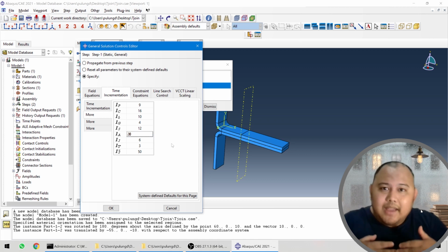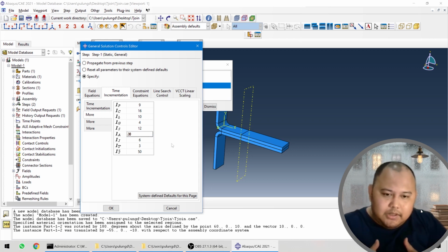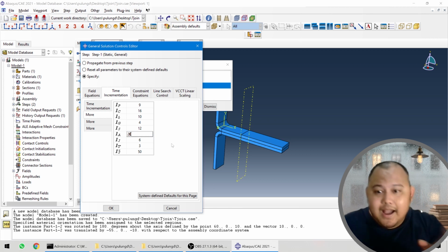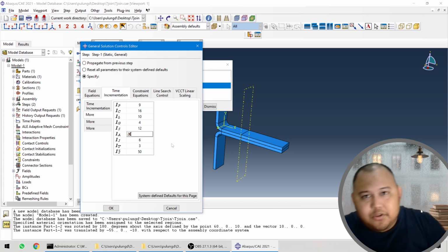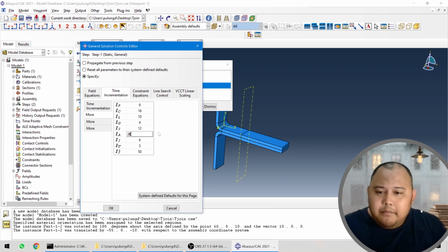Okay, so for a certain note that you gave, Abaqus might need to do it in so many very small increments, right? So the IA, on the other hand, or the IR or I0, is basically how many iterations you allow Abaqus.